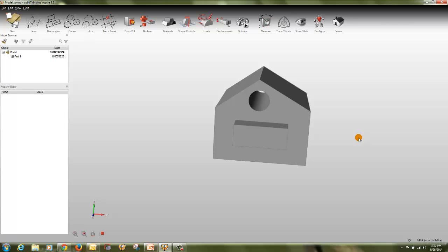Sketching tools are used to build or modify parts by drawing sketch curves. A curve is a wire entity such as a line, rectangle, circle or arc. Closed loops of curves automatically generate faces that can be pulled into solids when you exit sketching mode. Sketching curves on an existing face breaks the face into subfaces. These can be extruded into solid material by pulling outward with the push pull tool, or turned into a hole by pushing inward.